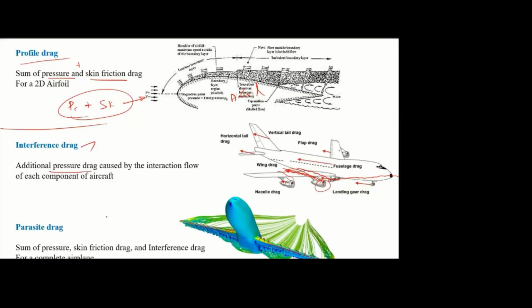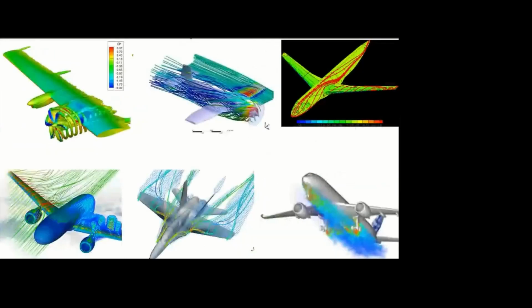So here I can explain. You see, without this propeller, the flow is smooth on the airfoil. So here we may have less drag. But see here, because of this rotating propeller, we are having the disturbed flow. That disturbed flow affects the flow over the airfoil, so the drag is increased.